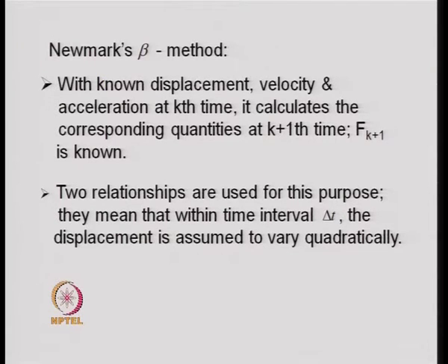The advantage of this solution is that if f tau, or the force, is not an integrable one, then in any way one has to go for a numerical integration. So, instead of doing that numerical integration, one is using the known solution for a triangular pulse, rectangular pulse, and a damped free oscillation. So, using these three solutions, you are able to tackle the problem.